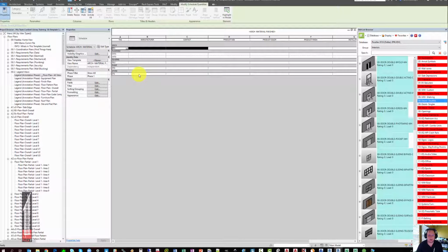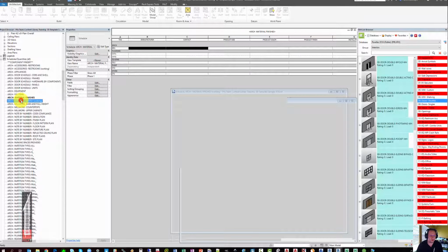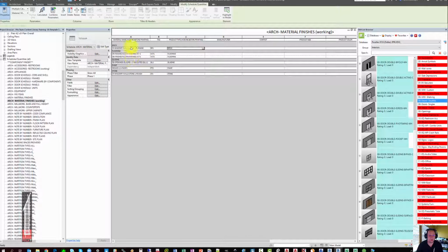However, some teams have taken to placing floors in what they call a material garden. That way they can pre-populate the list of finishes that they would like to see in the schedule prior to having the model completed. Keep in mind that if your project team does this, you'll need to visit wherever they have modeled the material garden to get items to disappear from this list. That's all of how to use the material finish legends. So that should have you able to create and classify your different materials going forward.